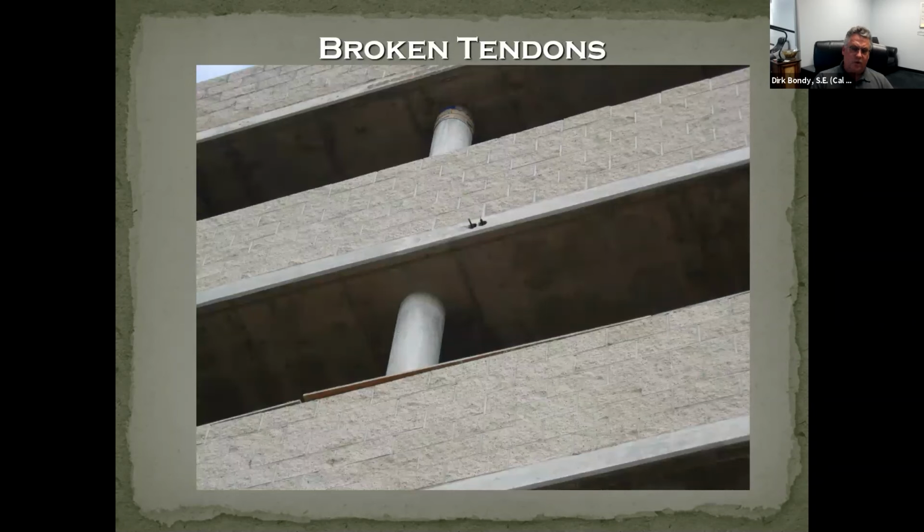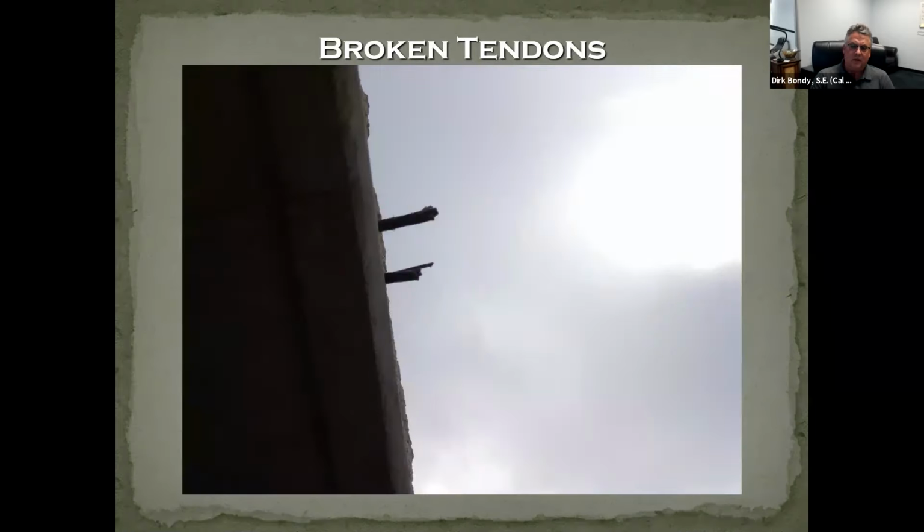A post-tension structure will talk to you also. When post-tensioning strands fail or rupture for some reason, they'll poke out of the building, say hi to you, say, hey, look at me, something is wrong, Mr. or Mrs. Engineer, you need to address this. This is the same structure from below, but the post-tensioning tendons will just pop the grout pocket, shoot it out, and come out of the building. But again, concrete is great at expressing itself to you. So it's showing you that something is wrong.